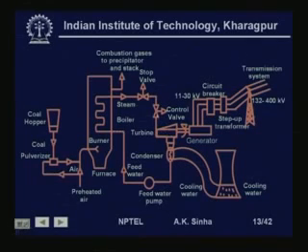So, in the turbine, this steam goes in, high pressure, high temperature steam, which rotates this turbine. The shaft of this turbine is connected to the shaft of a generator, which is a synchronous generator, a three-phase synchronous generator mostly. The generation voltage normally is in the range of 11 kV to 30 kV. This three-phase voltage, by means of circuit breakers and this step-up transformer, is stepped up to the transmission voltage level, which is 132 kV to 400 kV line-to-line voltages. So, this is how it goes.